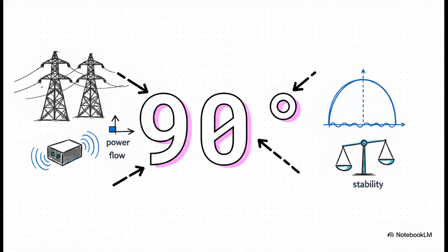Moving to slide 16. Listen up, class. If you take away just one number from these standard derivations today, make it 90 degrees. In our standard AC transmission equations, maximum power transfer occurs right when the power angle hits 90 degrees. Now, a STATCOM's dynamic nature can actually push that absolute maximum power threshold to an angle somewhere between 90 and 180 degrees, depending on the current injected.